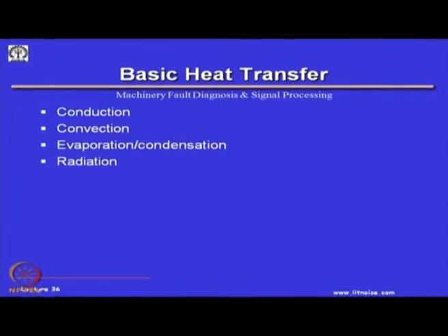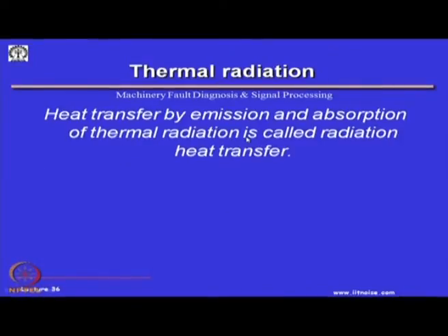So, we just mentioned conduction, convection, radiation. Heat transfer by emission and absorption of thermal radiation is called radiation heat transfer, and I was telling you radiation heat transfer is what we are going to take help of to estimate the temperature of the bodies by thermography.